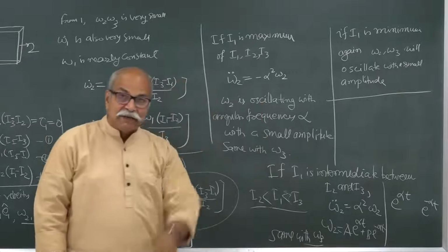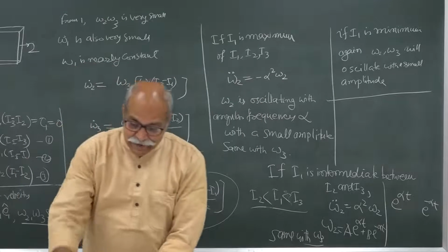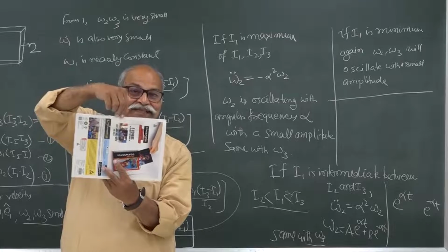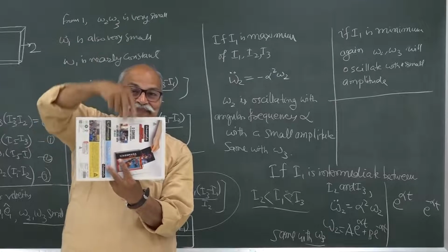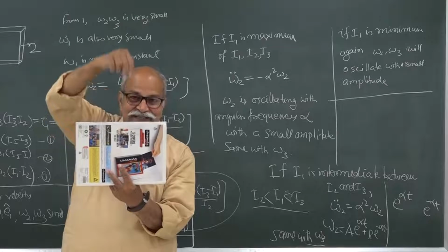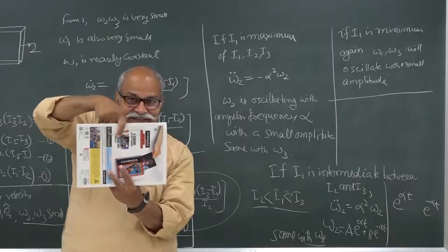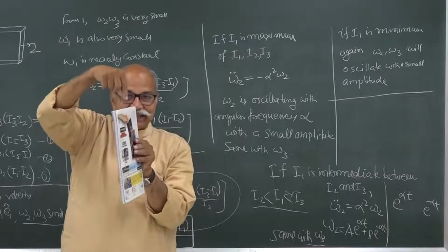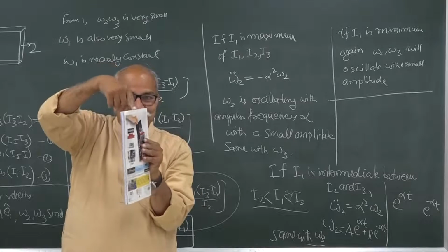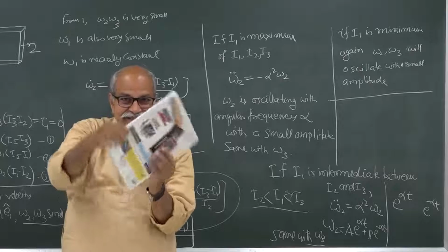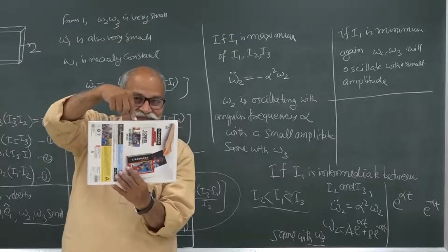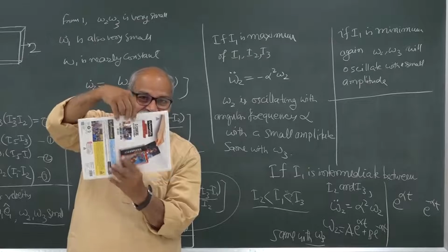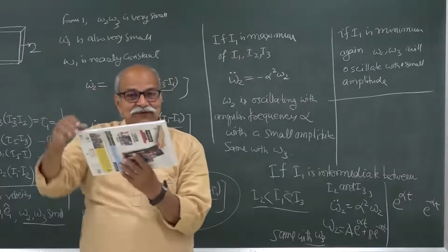So, this is not stable. When I am rotating it this way to start the motion, I am using the intermediate moment of inertia of this plate, which is intermediate between about this and about this. This is the smallest, masses are close to the axis. Then this is a little bit larger, m L square by 12, m b square by 12, and then this is the sum of these two. So, that is what you have seen.